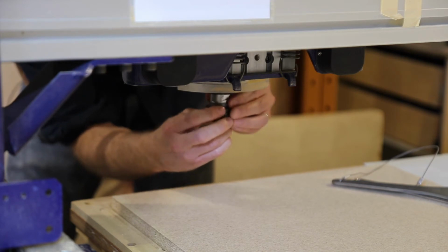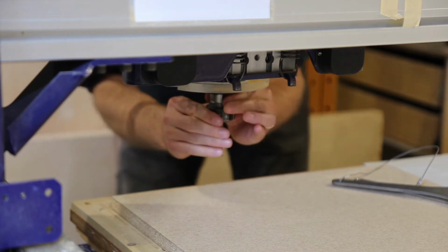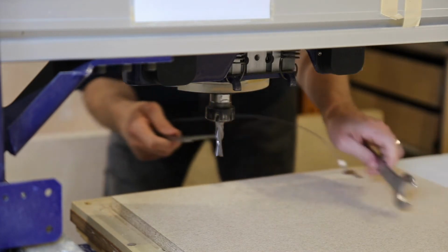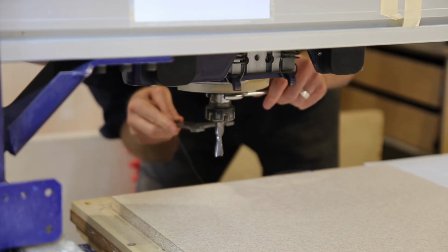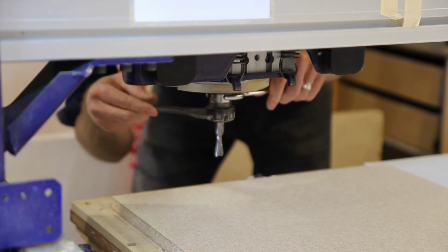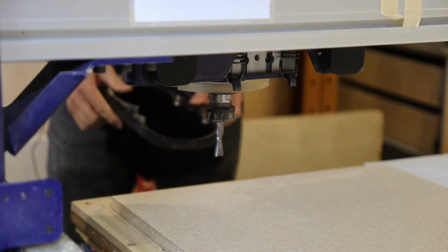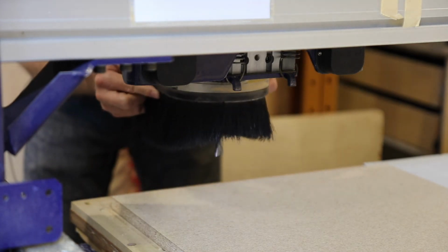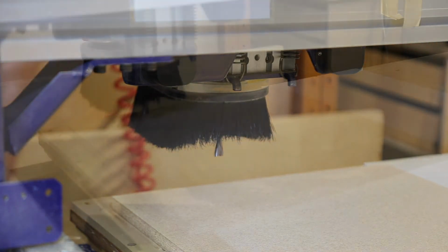Tighten the nut finger tight, gripping the bit in the collet, and place the silver offset wrench on the spindle shaft flaps. Slide the studded wrench onto the collet nut from below and tighten the collet nut. Be sure to tighten the nut sufficiently, otherwise your bit may slip down out of the collet, ruining your workpiece. Once you've set your bit, install the magnetic dust shroud to ensure optimal chip removal.